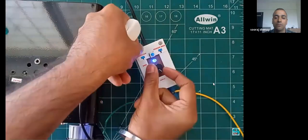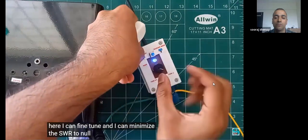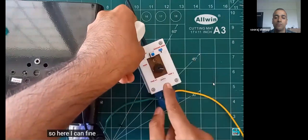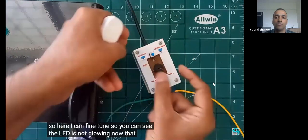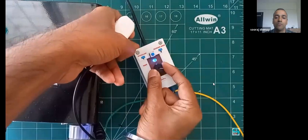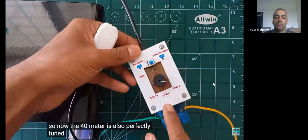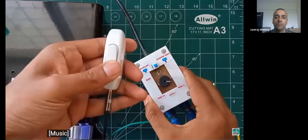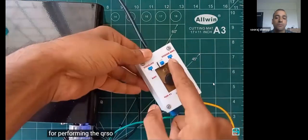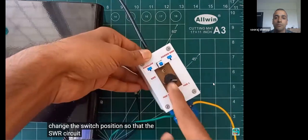Here I can fine tune and I can minimize the SWR to null. So you can see the LED is not glowing now. That means the SWR is very minimum. So now the 40 meter is also perfectly tuned. For performing the QSO, again we need to change the switch position so that the SWR circuit gets bypassed and it will work as an end-fed antenna.